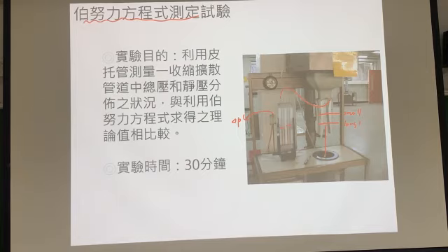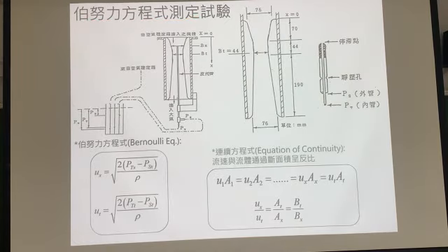And this is the Pitot tube. You can change the Pitot tube to different locations. At a different location, we have different velocities, and with different velocity, you can observe a different delta P recorded in here.